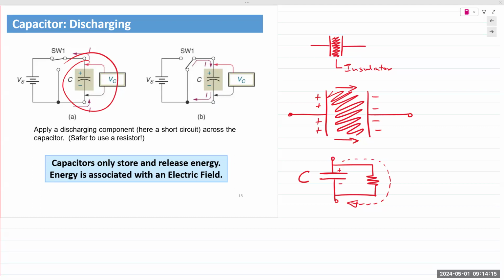There are videos online where you can actually see this. If you take a small charged capacitor, take it out of the circuit and short the two leads together, what happens? R, the resistance, is now 0 because of the short between the terminals of the capacitor, right? A charged capacitor is like a battery. It stored energy. You short the two terminals of a battery, what happens? All of that energy is discharged through that pathway. That pathway has low resistance, a short circuit, very close to 0 ohms. So if R is 0, I is infinity. All of that stored energy is released in an instant.